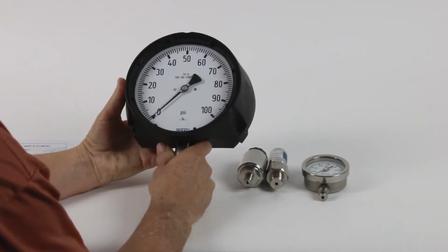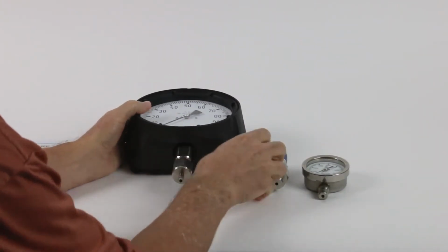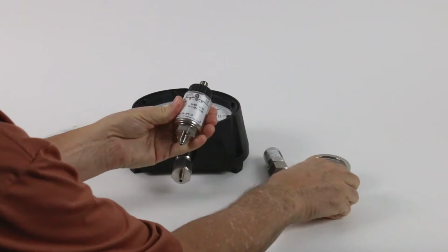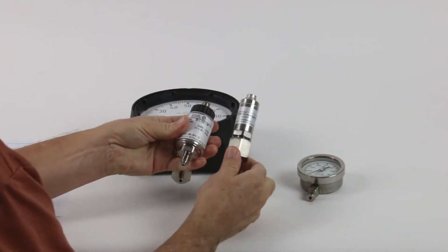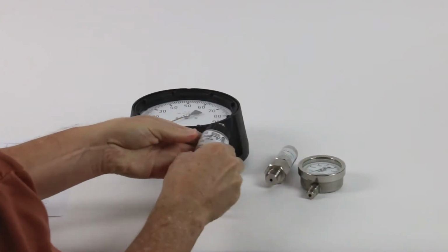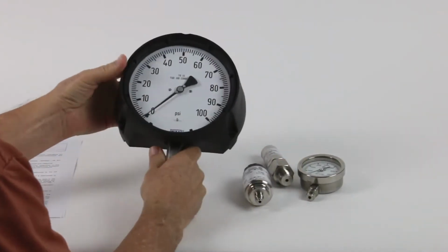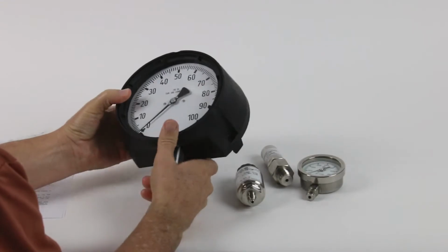Once the appropriate level of calibration is determined and the capable personnel are identified, the next step is to determine the range and accuracy of the device being tested, as well as the required range and accuracy for the pressure standard that will be used. The ratio between the accuracy of the standard and the device under test is called the test accuracy ratio.